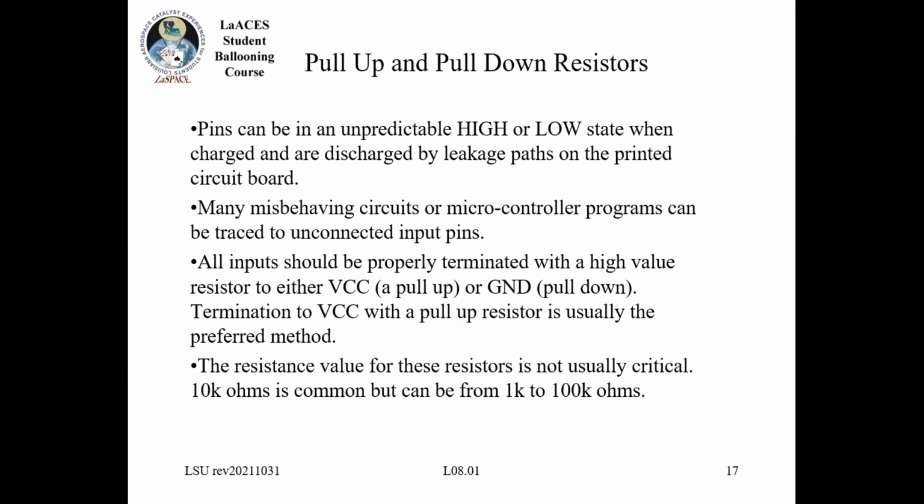So because of this, like I said, you pretty much always want to use a pull-up or pull-down resistor. Usually the actual value doesn't matter that much, right? Because I'm not actually looking for a particular resistance. I'm just trying to put some resistance between the input pin and either the ground or the voltage source so that I have that voltage drop.